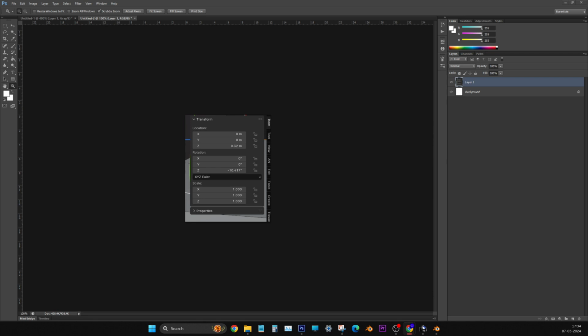You type now, have a look there. Type now 0.01. Point, okay, 0.01. Enter. You see, removed one vertices above the folder icon.